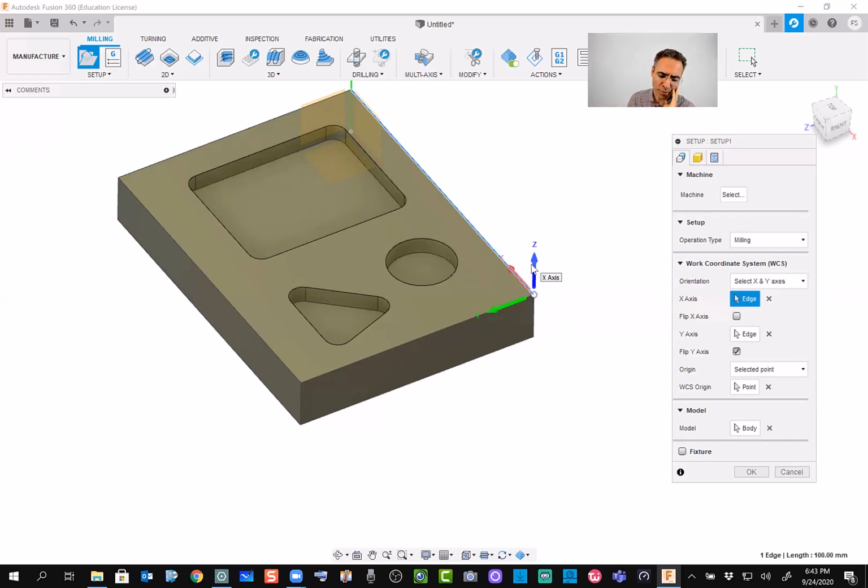As a general rule of thumb, Z is the tool, and when it creates this pocket, it's going down, right? Going down means negative, means removing material, stepping down. So that's why this Z axis should go up, normal to the plane. Soon it will become clear why I selected this X, Y, Z. So far, is it clear, Ahmad? Are we good? Yes, everything's good.